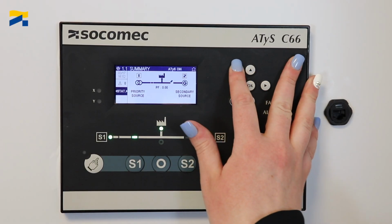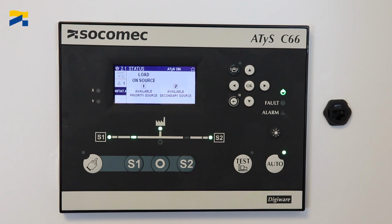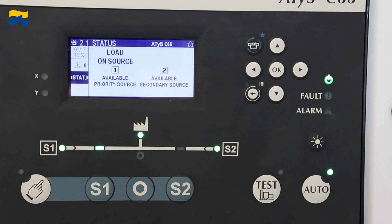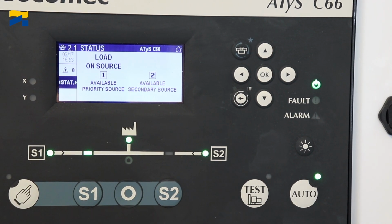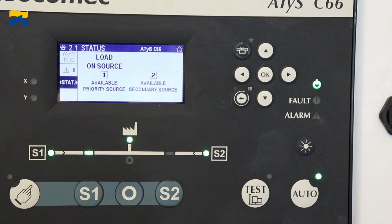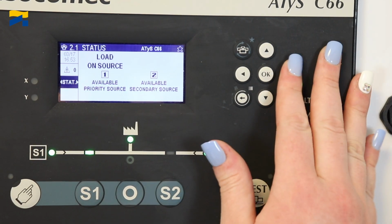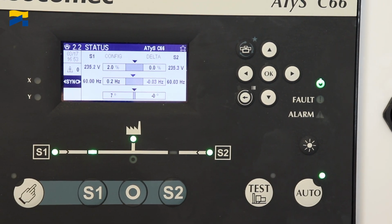The next dashboard is the Status dashboard. This gives you more detailed information on the supply sources. This dashboard also has sub-menus. The first sub-menu is Stat, which informs you on the availability of each source. Then, using the navigation arrows, the other sub-menu is Sync, which gives you information on the voltage, frequency, and phase angle of both sources.